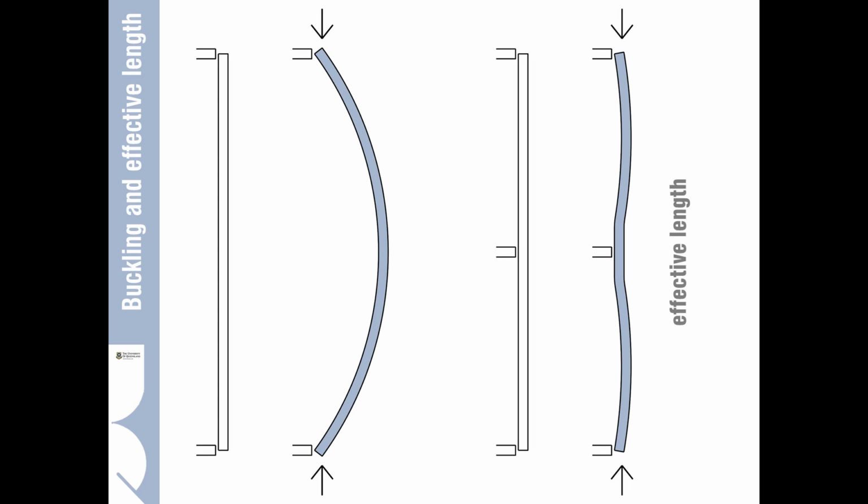And it's where things like the effective length of a steel member come much more into play. So although a steel element can be quite long and span quite a long way, often we need to reduce its effective length by pinning it back to a rigid structure to reduce the overall effective length and to reduce its propensity to buckle.